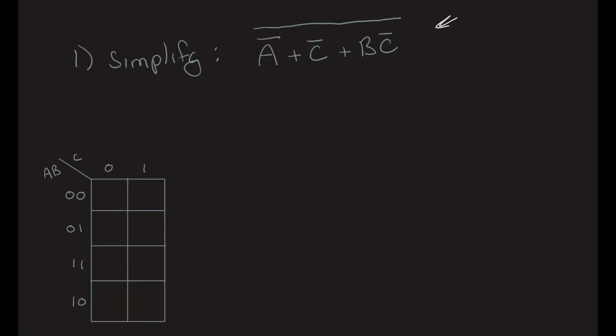Well, we're going all the way back to the beginning. Step 1, De Morgan. Alright, so this is one of the tricky ones we have to De Morgan. Remember, I see the bar over a few things. I see it over this, then over this, then over this, then over this, then over this whole thing. I'm not going to skip steps. So I've got A, not, this OR becomes an AND. C, not, this OR becomes an AND. And then I've got it over B, C, not. You're going to see why in just a second it's important I don't skip steps.